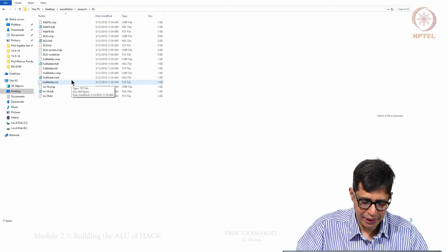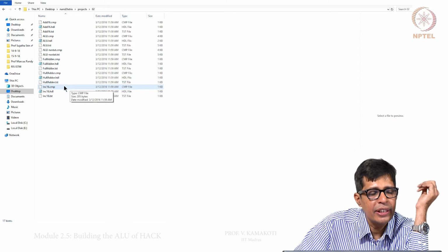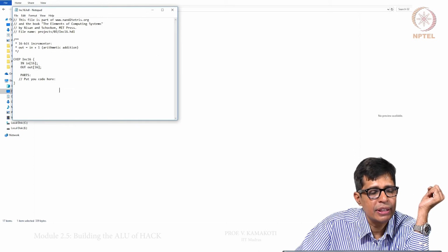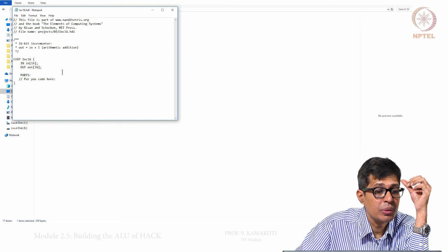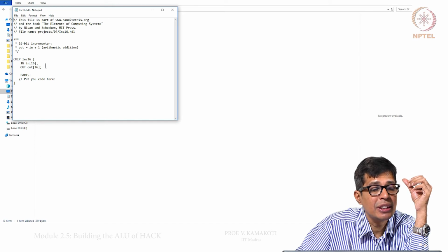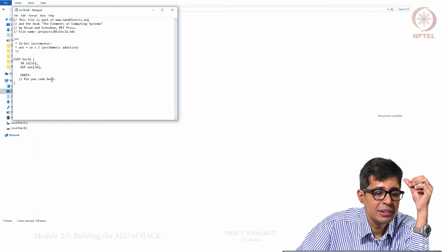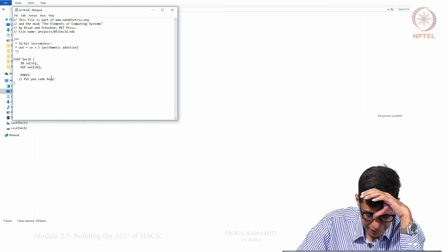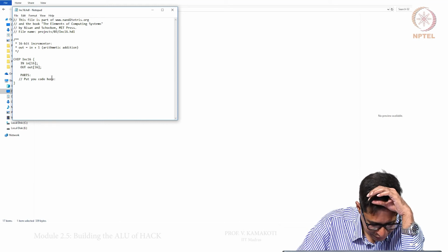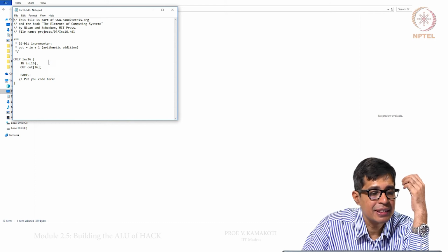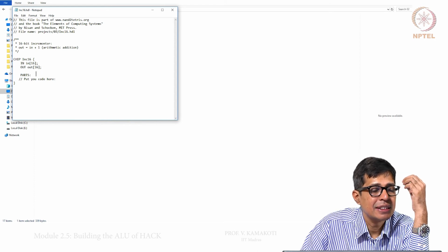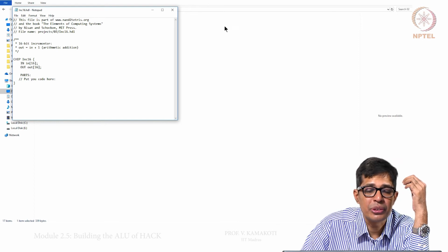16-bit incrementing. So, this is an increment of 16-bit. The input should be incremented by 1. You can actually use a full adder to increment this by 1. There can be some other, more intelligent way of doing this also, if we can try that, but nevertheless just use a 16-bit adder to do this increment.